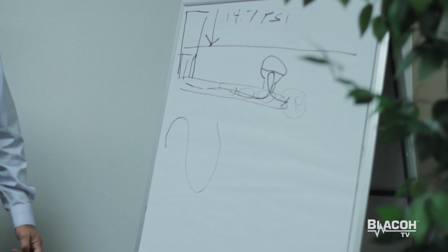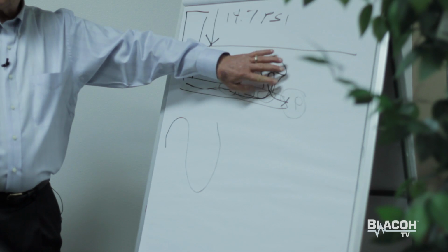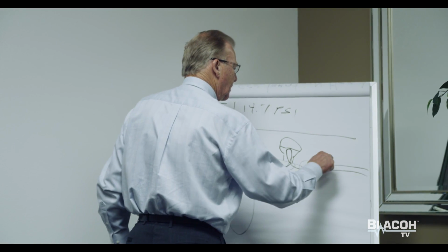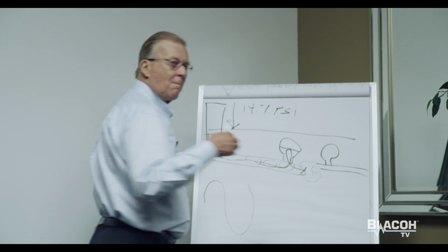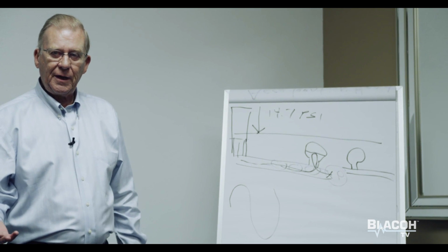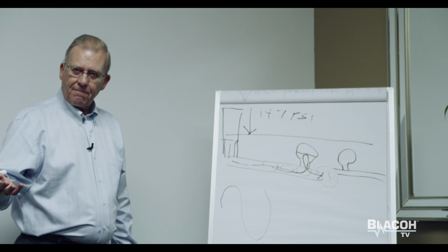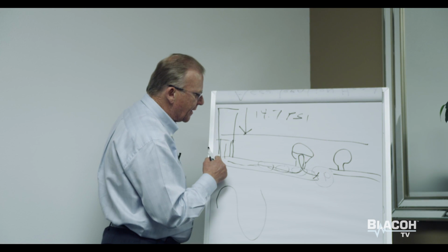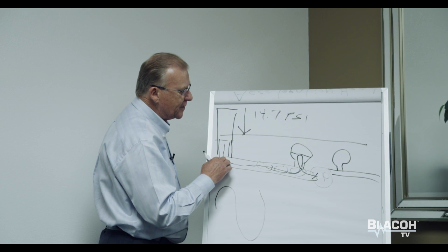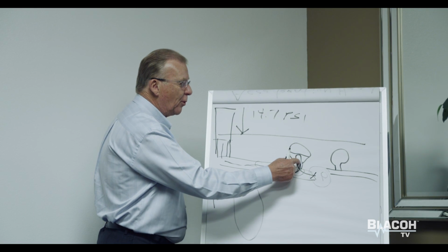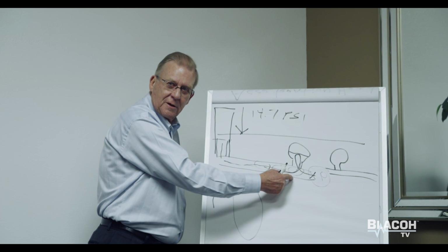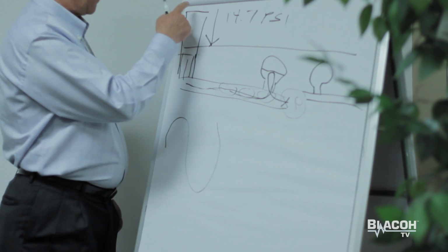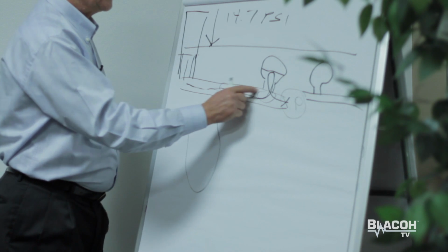In order for the inlet stabilizer or the pulsation dampener on the discharge to control or minimize acceleration head, it must be properly located. For example, the inlet stabilizer is going to handle this acceleration head up to the point where the dampener is installed in the system. Not between the pump and the dampener, but from the beginning source of the liquid to the dampener.